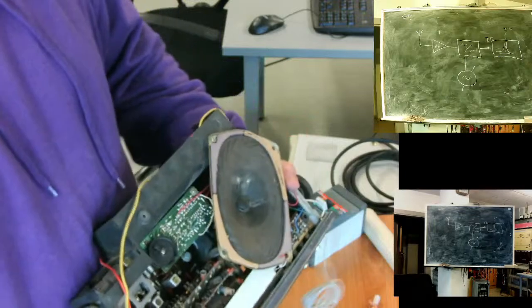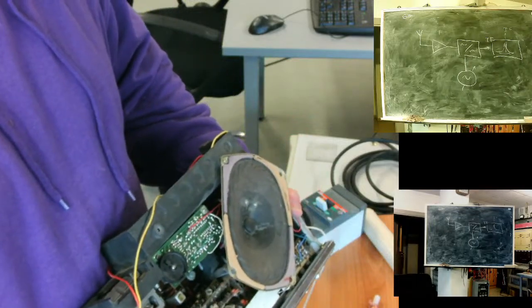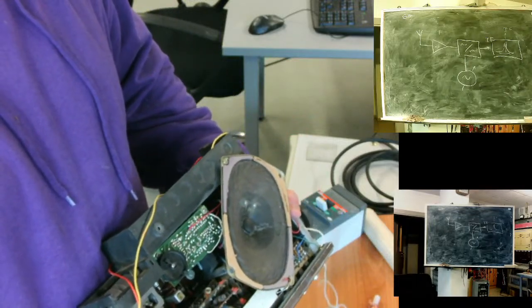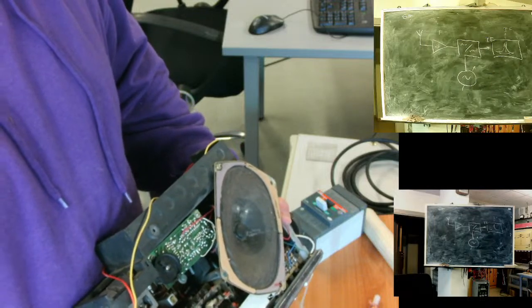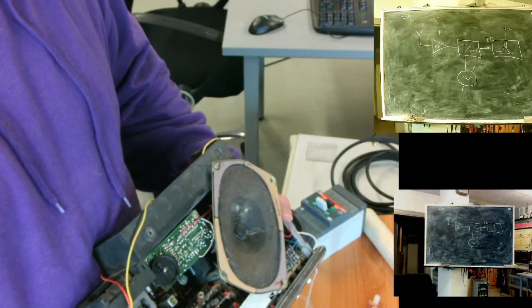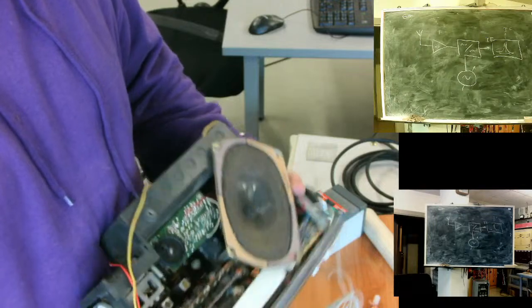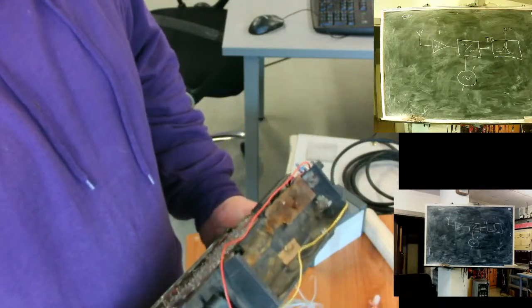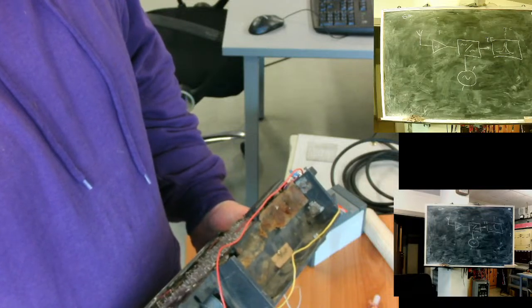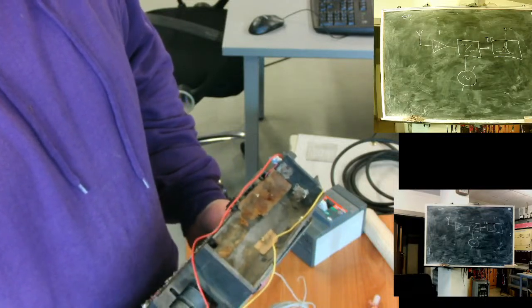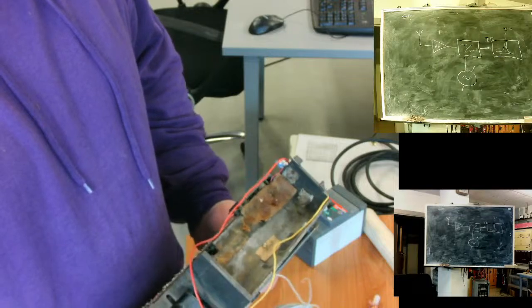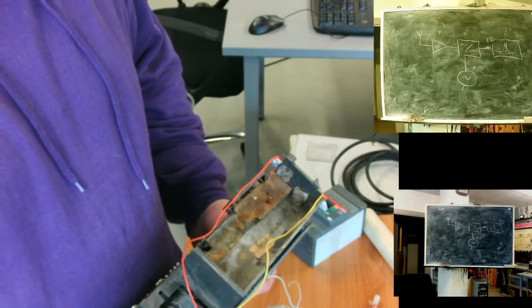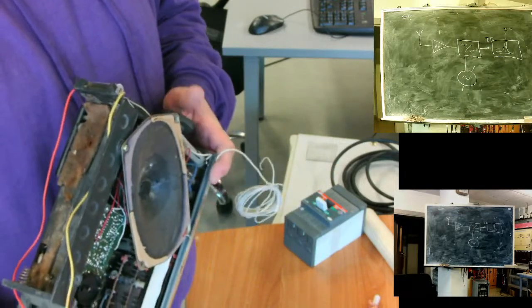Here we have one coil for the heterodyne, one coil for the input amplifier, one for the signal. One variable condenser with 2 sections: one changes the heterodyne frequency, one is selective.